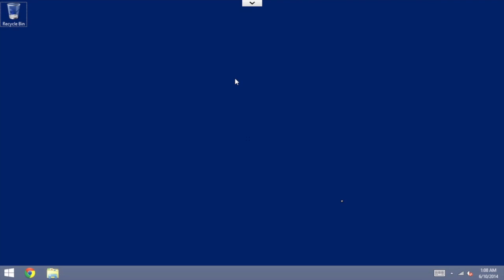Okay, so we're now going to install Replicator G on Windows. If you're running a version of Windows 8 or later and it's a 64-bit version, there is a little step you have to do first, which is to disable driver signature enforcement. These are not signed drivers, and therefore the only way we can install them is to disable that setting.